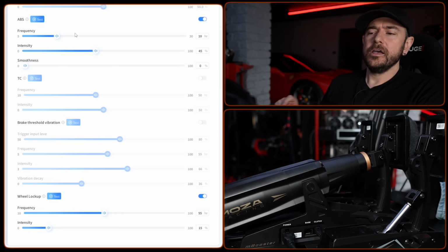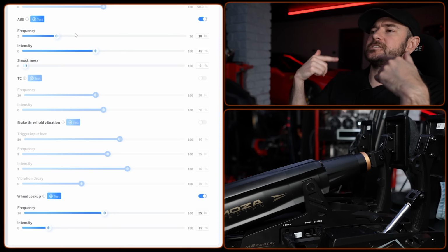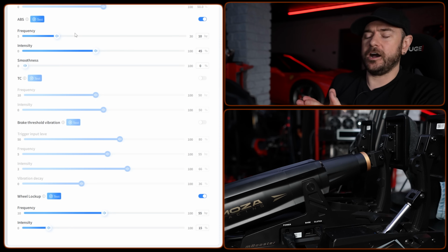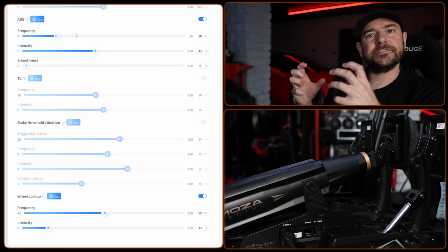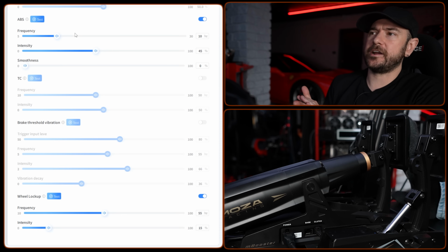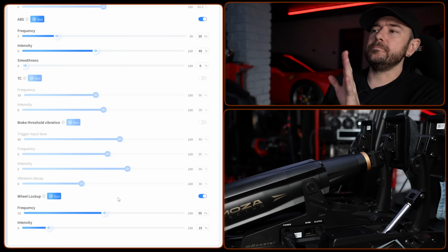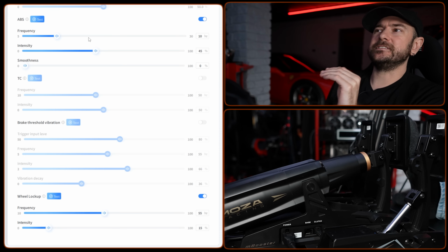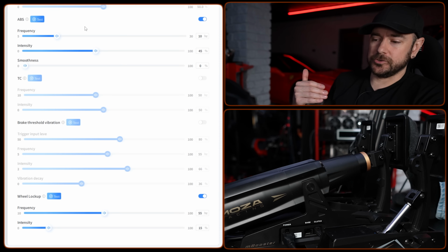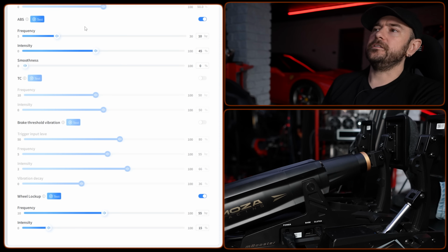Now, in a race car, you typically will have an adjustment for the ABS level. And what that allows is slight under rotation of the tires. Tires will actually produce the most grip when they are just slightly under rotating, but not completely sliding across the track surface. So that is the reason why you may still want to have a little bit of lockup here just to feel where that under rotation is occurring, because the ABS isn't necessarily going to allow you to absolutely optimally brake into every single corner.